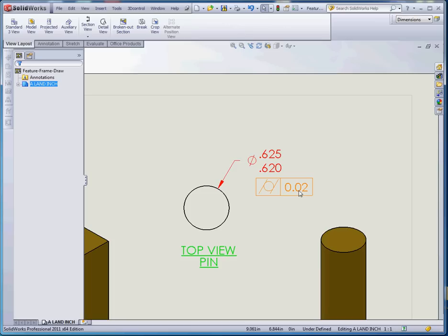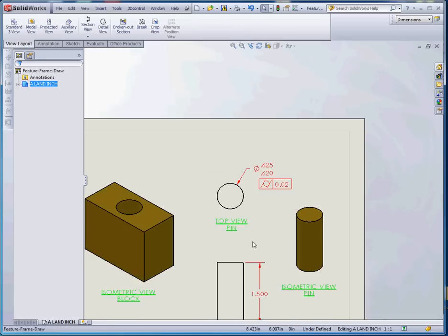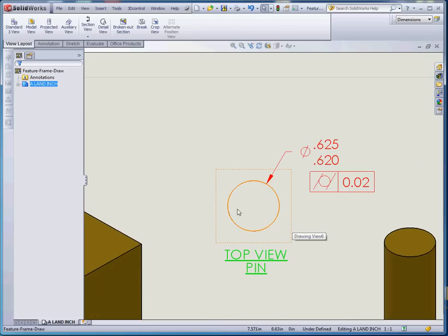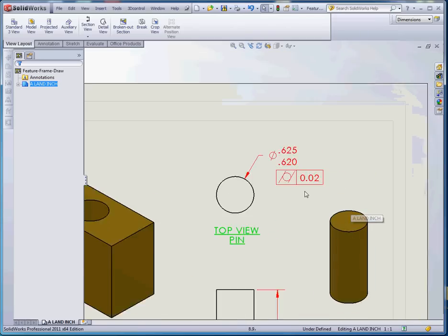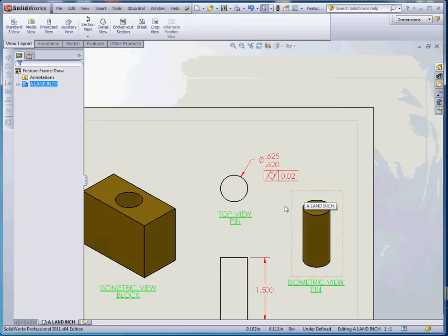So it has that variation to it. Between the top and the bottom, the cylindricity of that feature can vary by 20 thousandths of an inch. If you think about it, if we had a virtual cylinder, we can put this inside of this. That would be just a little bit larger than that, with a variation of 20 thousandths of an inch. Conceivably, we could drop that pin in a go or no-go sort of situation there, and it should be able to pass through that if it's within tolerance of this feature control frame, as it's stated. It should be able to pass through that cylinder.